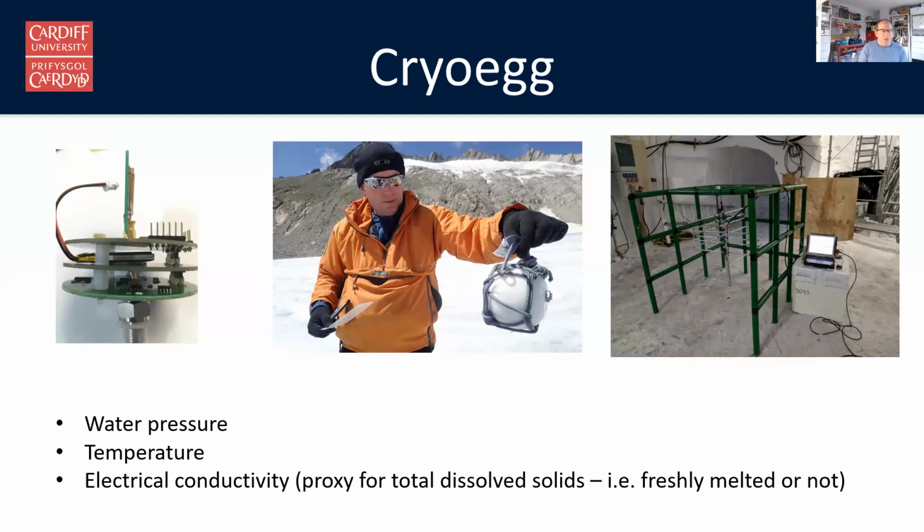My role essentially was to redesign the electronics in Cryoegg from the previous version that had been designed at Bristol. Essentially because a load of components were obsolete, and it seemed like a good idea to start again. And here's the electronics on the left-hand part of the slide. So it's got the sensors in it, it's got a little processor and a battery, and then it's got a radio transmitter. And the thing that's unusual is that it reports its data by sending it wirelessly by radio through the ice to a receiver on the surface.